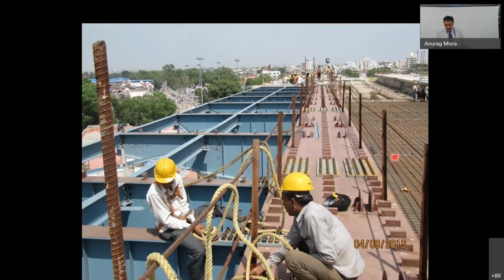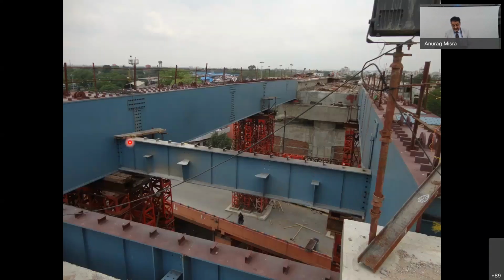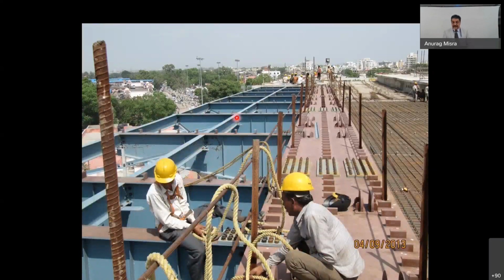So this is at a lower level, whereas the platform level is attached towards the top of the girder. If this is the depth of the girder, your platform is attached here, and the deck level is attached to the bottom of the girder. You can see this deck level is where the rail would come, attached to the bottom side, and the platform is cantilevering from the top of the girder, which would provide space for the passengers to board the train